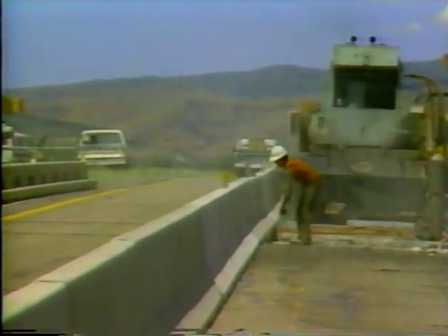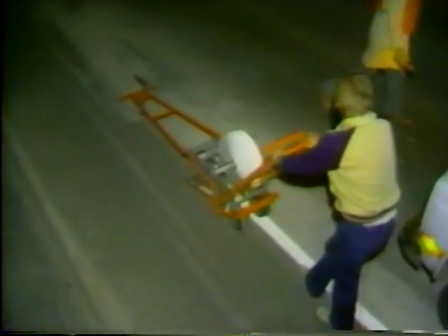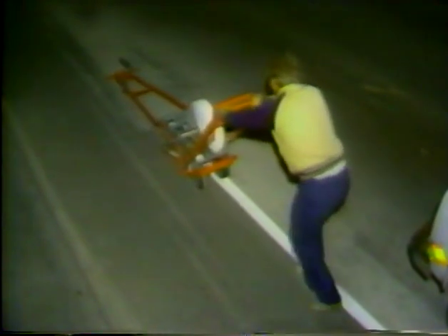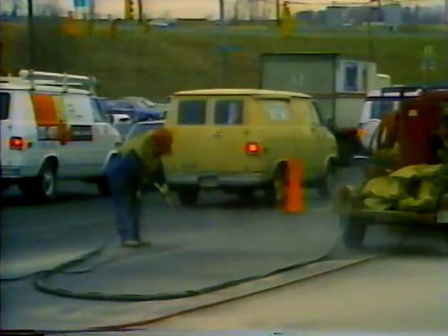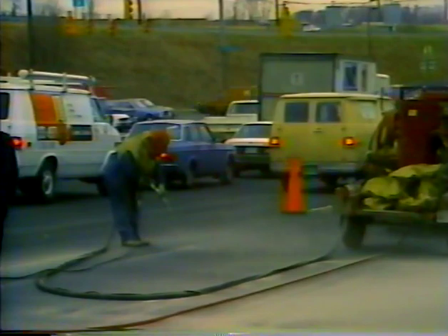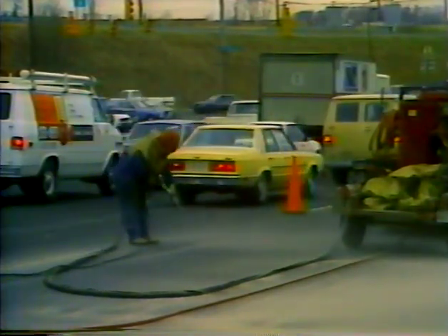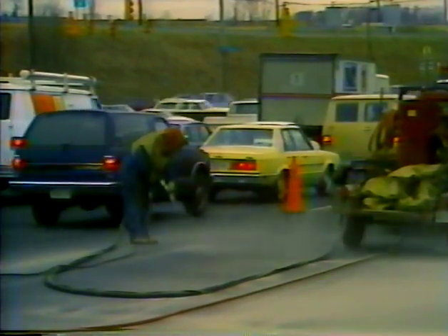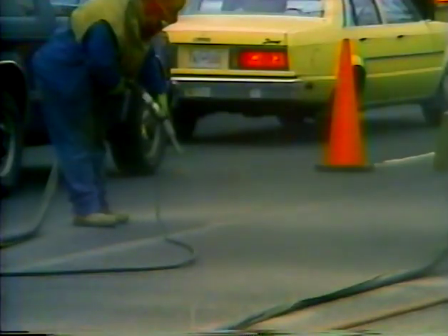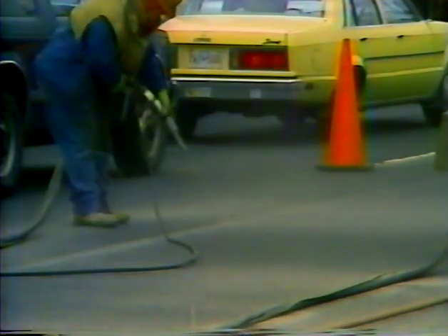better choice of device. You also should check the placement of temporary pavement markings. As with all devices, pavement markings must be the type specified and placed in the proper locations. When work zone markings will conflict with existing markings, the contractor may be required to remove the old lines by sandblasting or another approved method. Blacking out the old markings by painting them over is generally not allowed. Refer to the contract to find out how much removal is required and how it's to be measured and paid for.